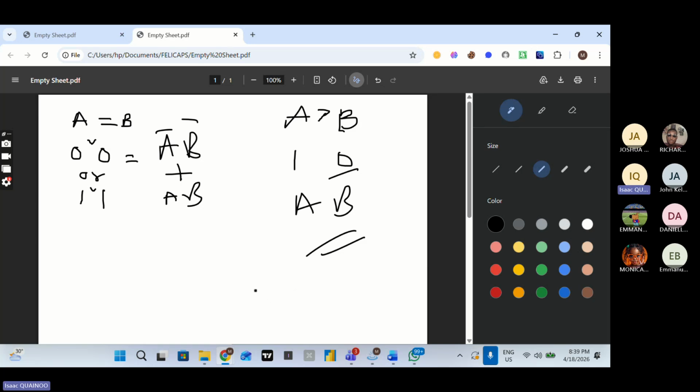Okay, and this same method is true for your 2-bit comparator. If you use the same method for your 2-bit comparator, you can still determine the expression without having to do your truth table. So with this, we are going to use an AND gate, right? With an AND gate, we have our A and then B naught. So for B naught, we have our B and a NOT gate right here. And then the output is A times B naught.